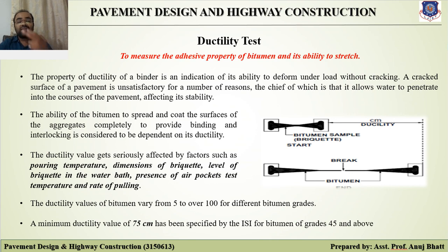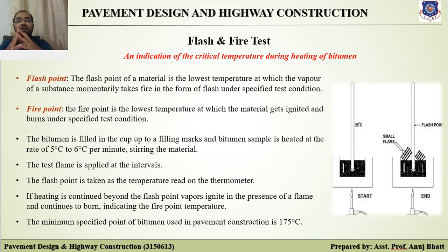Now the next test is the flash and fire test. Bituminous materials give out volatiles at a temperature depending upon their grade. These volatiles catch fire, causing a flash.